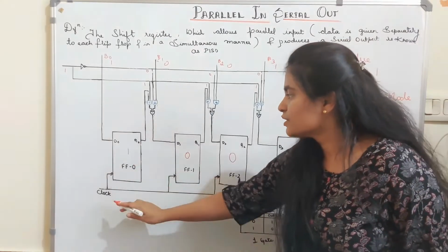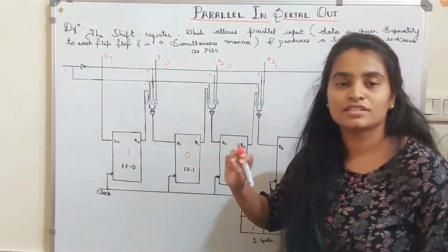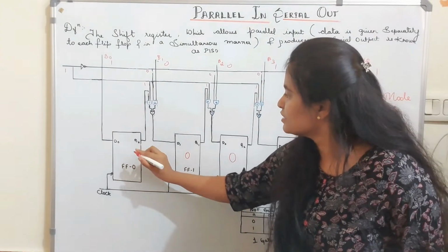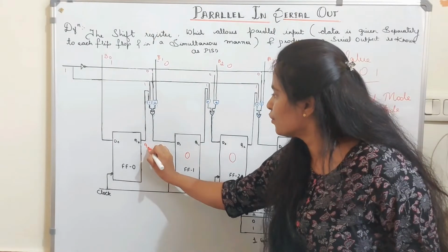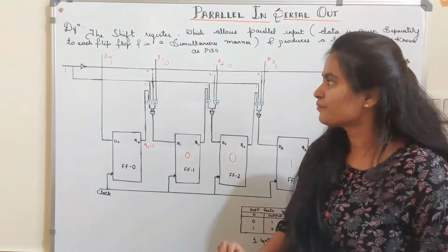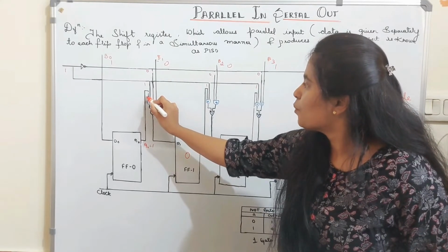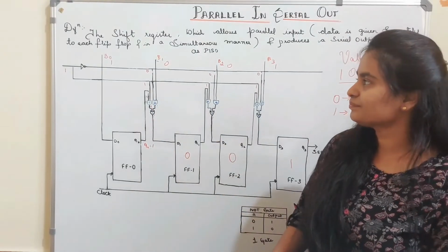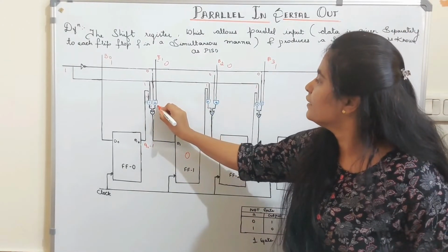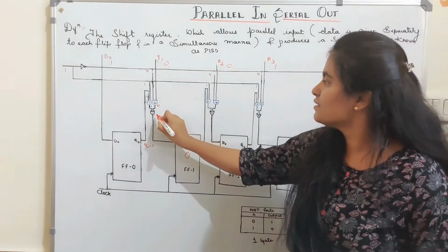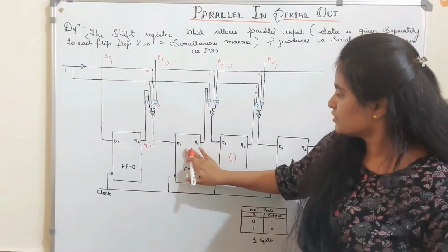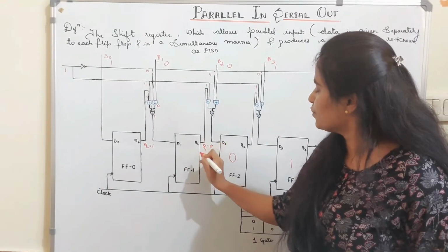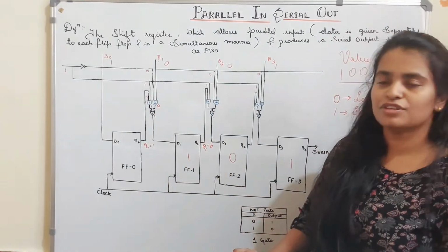So now let's see how exactly it works. Okay. So as you give a clock pulse, when the clock pulse is given to the flip-flop, what exactly happens? This one moves in from this location, that is Q0 is equal to 1. So the value here is 1. So 1 and 1, it is 1. 0 and 0 in AND gate, it is 0. 1 and 0 in OR gate, it is 1. So here the Q1 value turns into 0 and here 1 has been shifted.